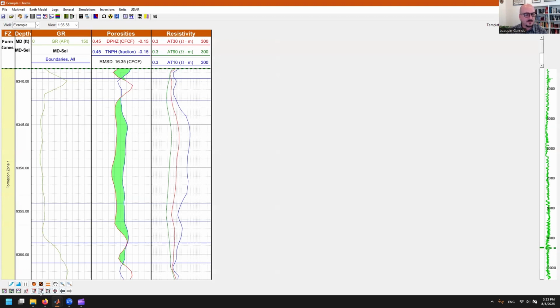All the controls that you have here, for example, this plus P is to create petrophysical boundaries. The arrow with the plus is to create boundaries. The difference between those two is just that the boundaries are more for fluid properties. And at this stage, it doesn't make any big difference, just use petrophysical. When we start looking into fluid flow and those modules, it's going to be more relevant. So for now, we stick with this.